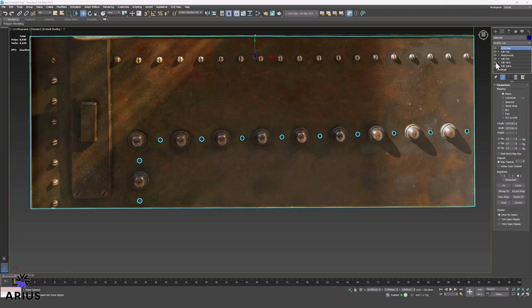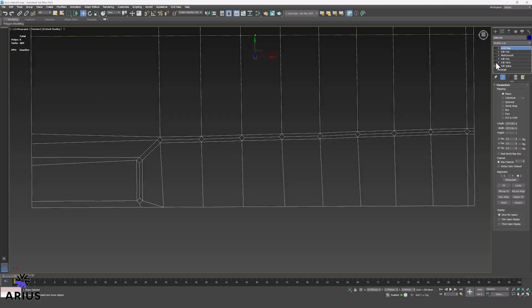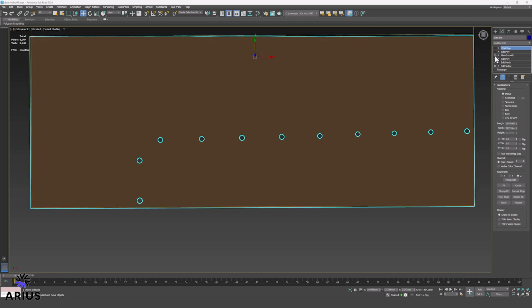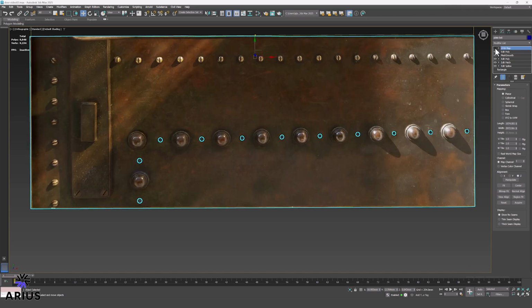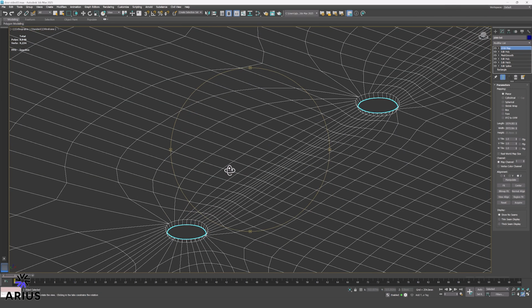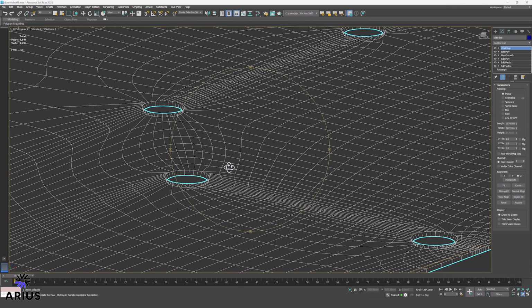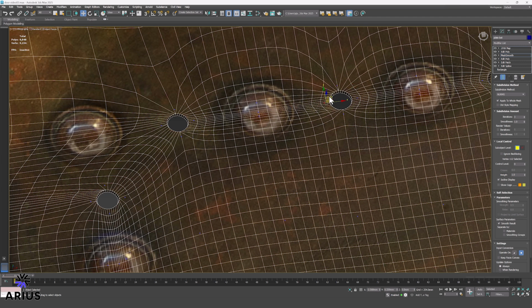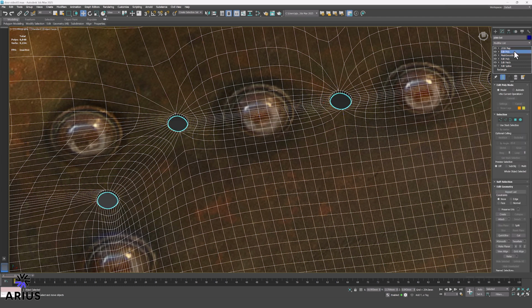However, the recess in the screw head needs somewhere to go below the plane, so make sure to create holes at each location at this stage before proceeding. Adjust the control vertex to match the edges of each hole in the plate, noting where some screws are slightly out of place. Scale in the bottom of each hole so the screw head has a receding surface to blend to.